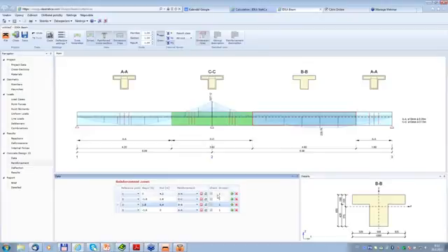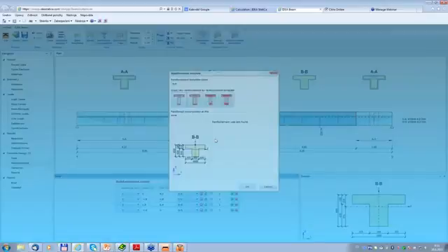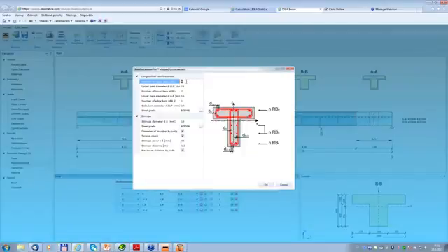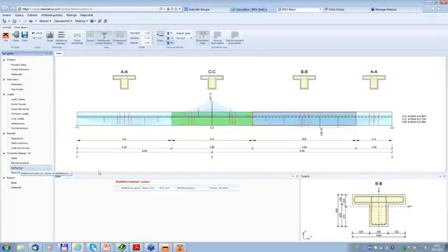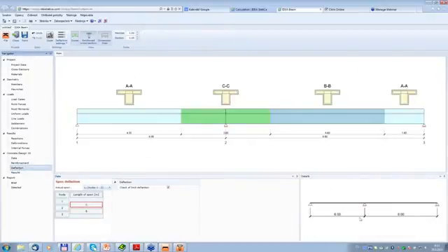And BB would be exactly the same. The reinforcement will be different. Upper bars will be diameter 10, lower bars will be 5 bars, diameter 16, and we need here also an edge bar. I wanted to save time, that's why I tuned the reinforcement before. I can see the settings for deflection, and I go to results.